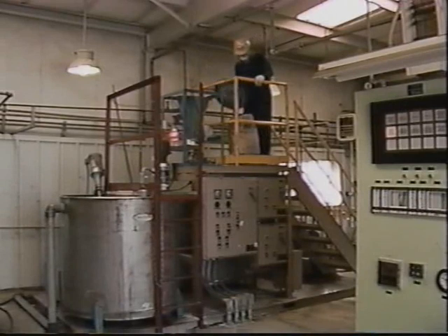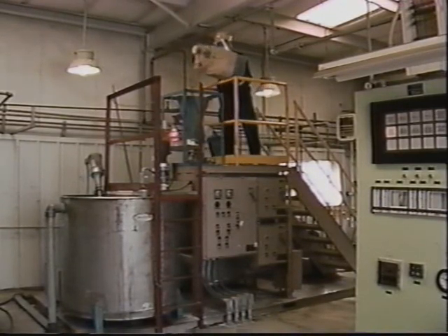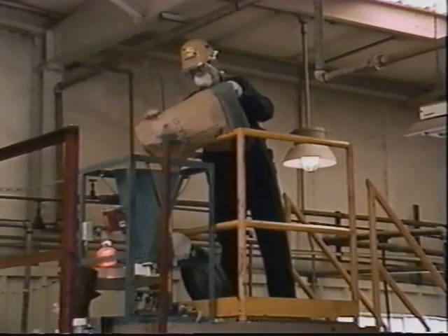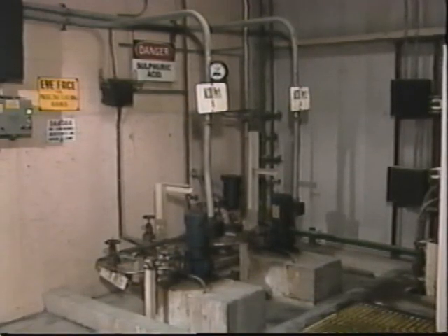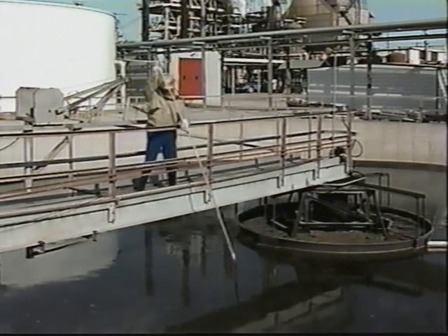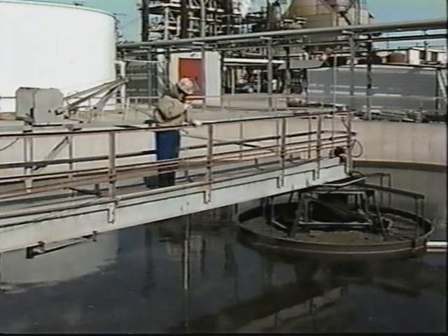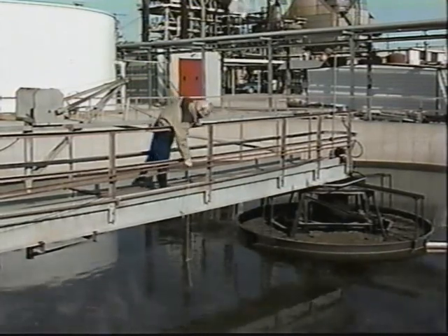If you recall, when the high sludge level was first detected, some pH adjustments were made to allow the water to be discharged to the environment. With the problem solved, the pH may now need to be readjusted to the original value. Also, the sludge recycling and wasting flow rates for secondary treatment will have to be checked once again and returned to their previous values if necessary. And of course, the operator will keep an eye on the clarifier sludge blanket levels throughout the system to make sure the screen repairs corrected the problem.